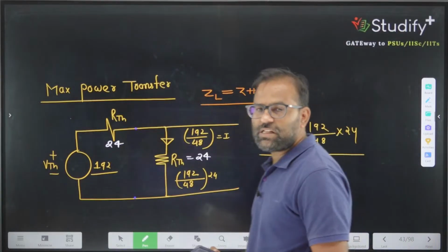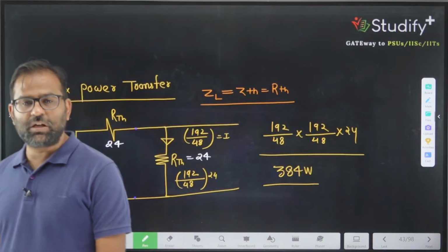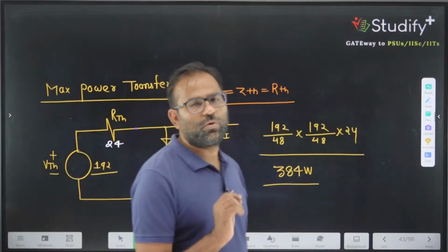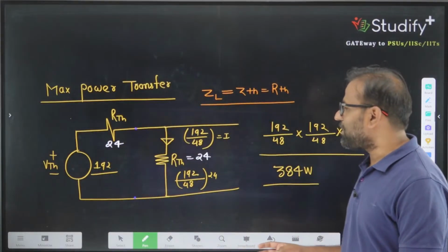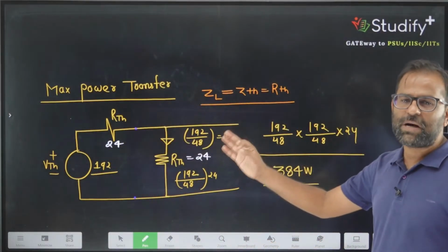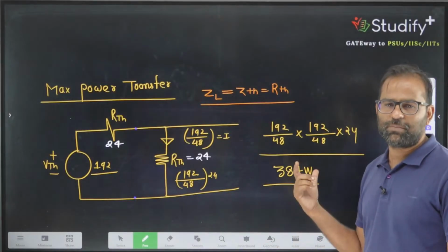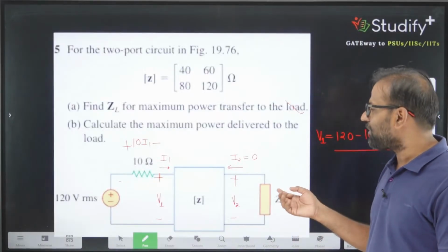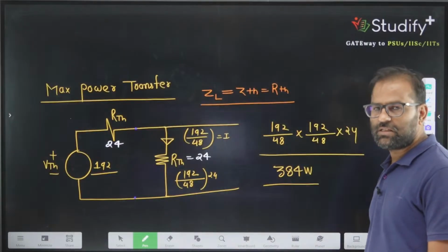So this is another category of question. They will ask questions related to the power transfer across any load. Whenever they ask a question about the power transfer or power across any load, try to convert your figure into the Thevenin's equivalent. This is the method.